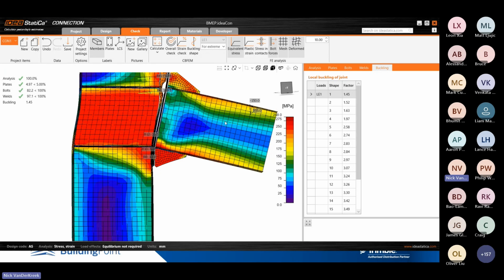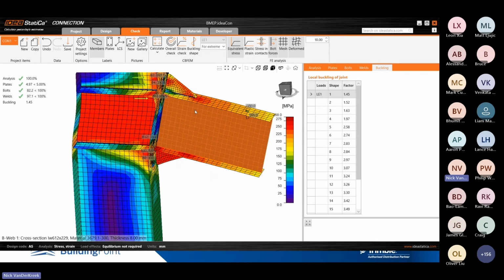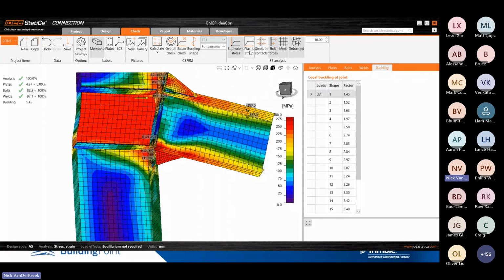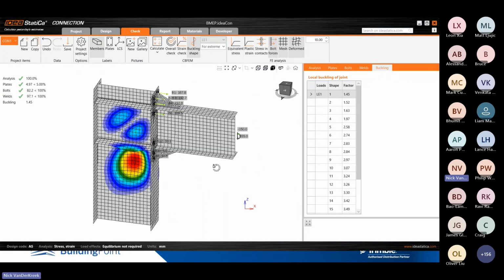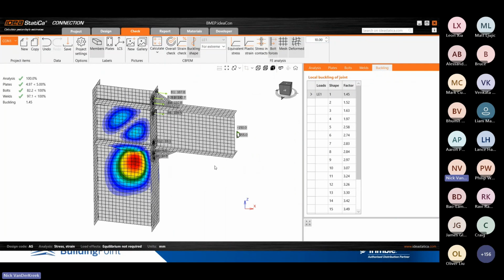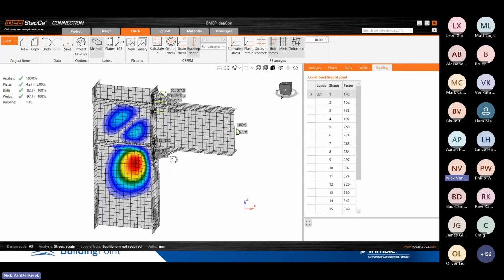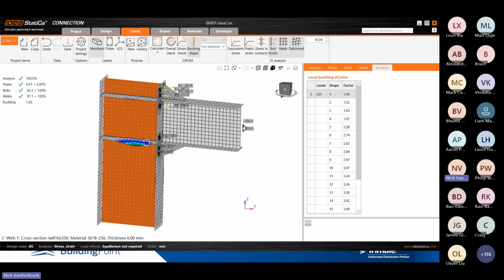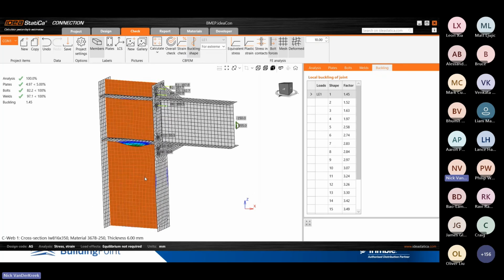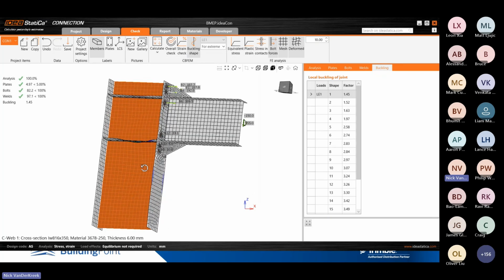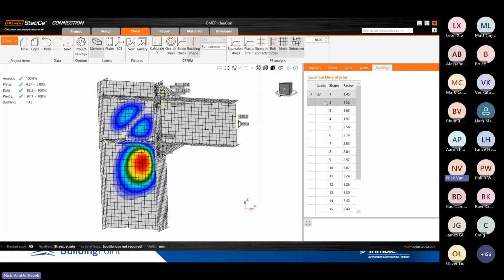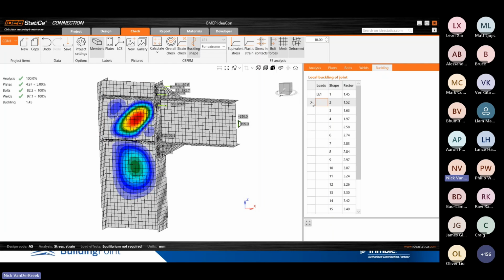We could also look at some other views and so forth, but that's something that I would tend to do to try to determine whether it's a connection factor, or just a member factor that would be checked by other things. But we're also seeing some buckling in that stiffener, perhaps in sympathy with that web buckle, but this is quite a low value, so I would be concerned, and I need to increase the stiffener thickness and so on, make some changes here.